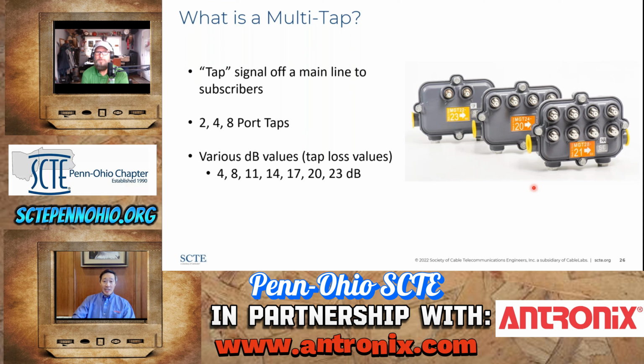So what is a multi-tap? A multi-tap, simply, taps off the main line to subscribers. A tap typically comes in a 2-port tap, 4-port tap, or an 8-port tap. Some people call them 2-way, 4-way, or 8-way. They come in various dB values, so you can see that on the label. It's a 20, 21, 23, various dB values associated with taps.